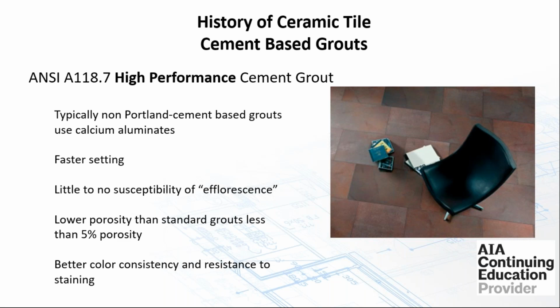This grout tends to cure from the inside out rather than from the outside in. So there is less effect by the elements of bright sun beating on it or wind blowing across it. And consequently, with this type of grout, you are going to have a more color consistent finish.